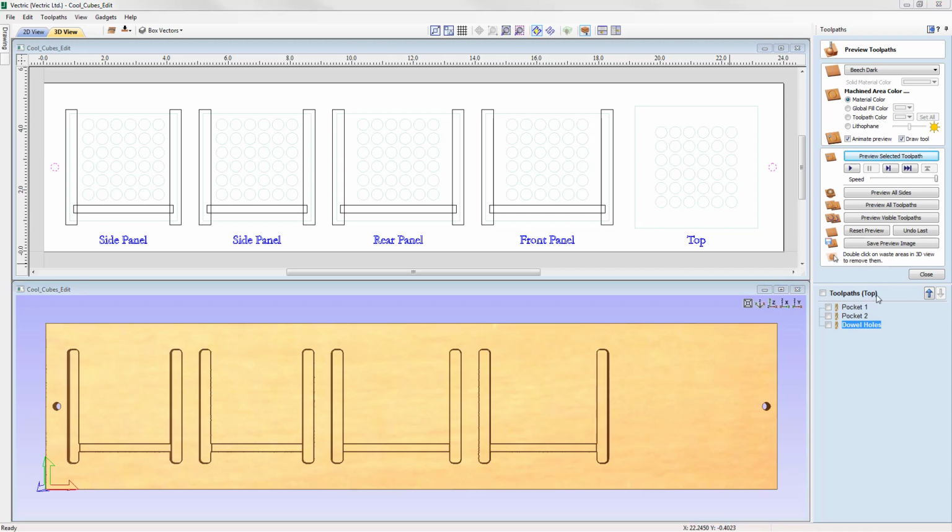And so in reality, after we've machined these 3 toolpaths, we'll take our material off of our machine bed, and we'll take the 2 dowels and we'd locate them into the holes that have been left in the spoil board from when we drilled through our material and into the board.